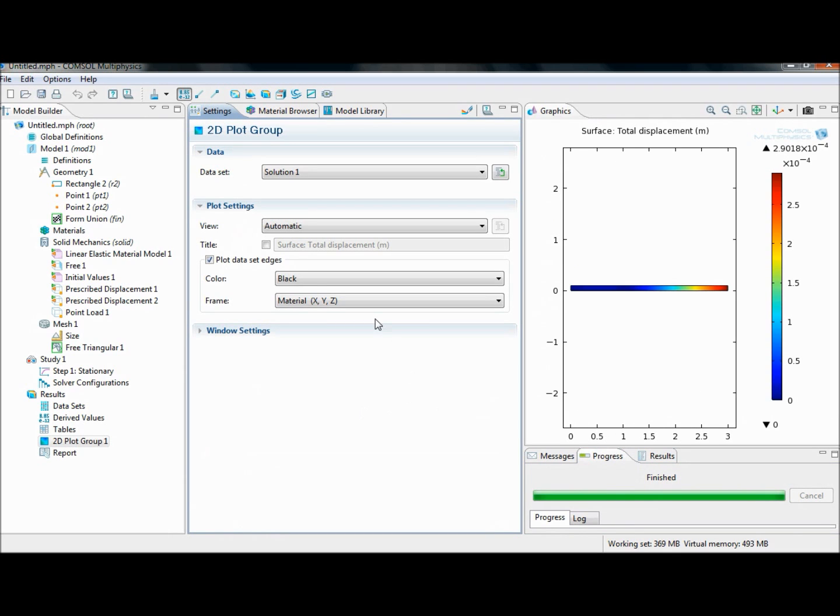So as you could see, it didn't need the density to be input in there. The density must be part of some of the equations. We could have taken a closer look at some of the equations. So what you can see is that we have a displacement of e to the minus 4. It's fairly low. It's very possible that the dimensions aren't reasonable here.